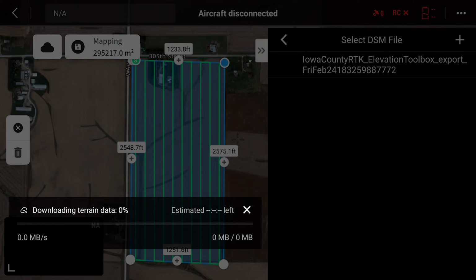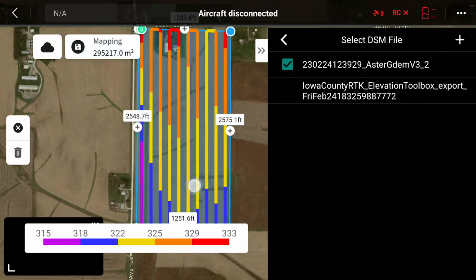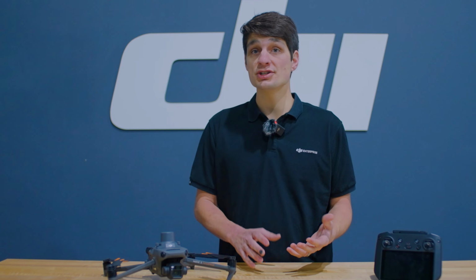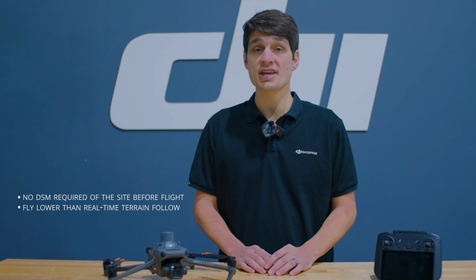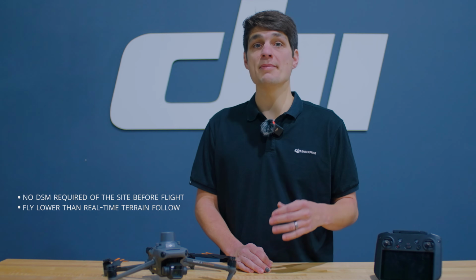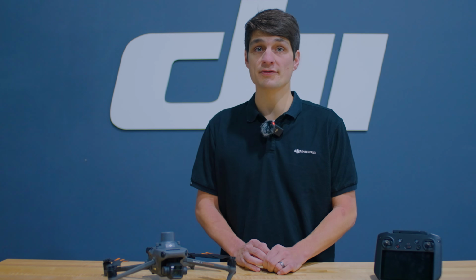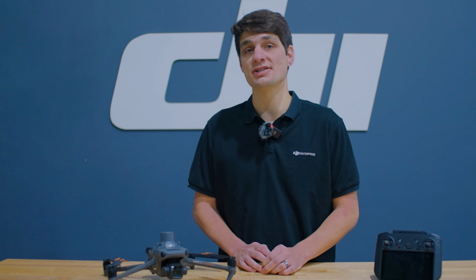Our source for our DSM is from Aster G-DEM V3 with a resolution of 30 meters. Some advantages to this tool is that no DSM is required of the site before flight, and you can fly much lower than real-time terrain follow. Some disadvantages are the low resolution of DSM at 30 meters and the inaccuracy and age of that DSM.